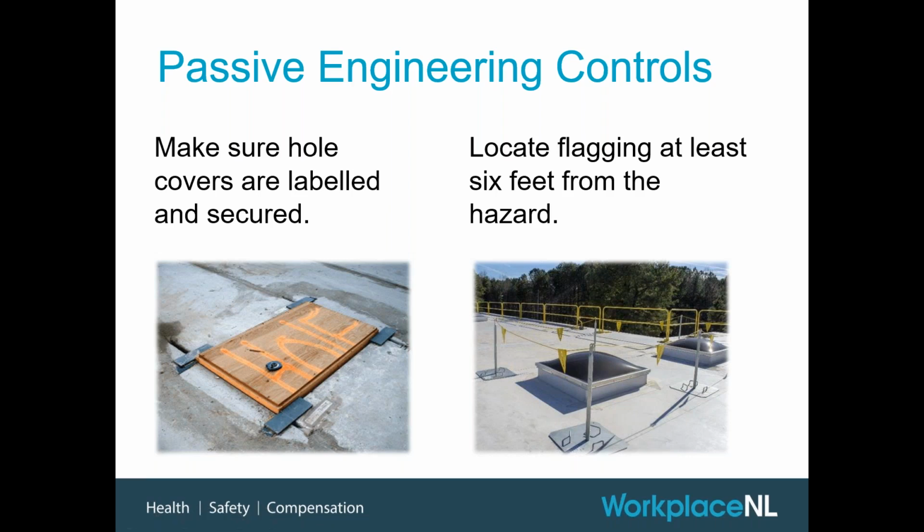But it's very important if you're using a hole cover that it is labeled and secured. So again, it shouldn't be able to be inadvertently moved. And if you are going to use flagging, which again is not my personal favorite here, primarily because we have so much wind and various other things, it's a good best practice to keep that 6 feet back from whatever the hazard is. Don't have it right at the opening or edge.